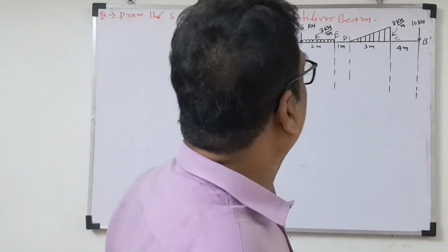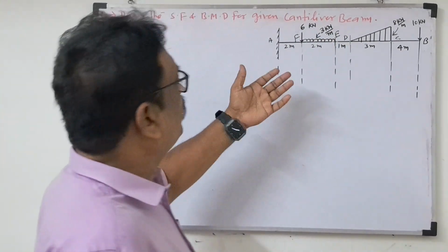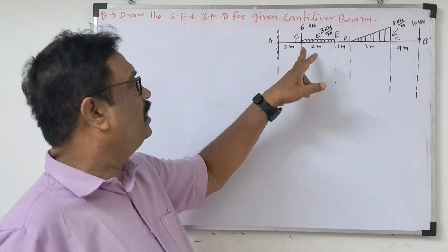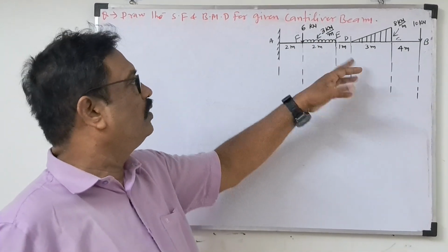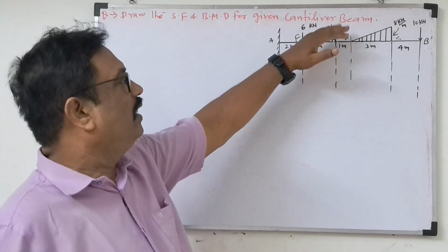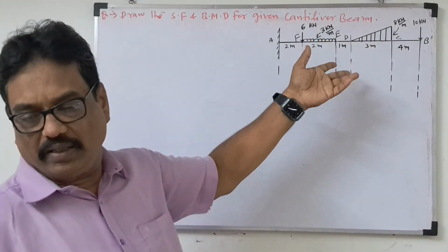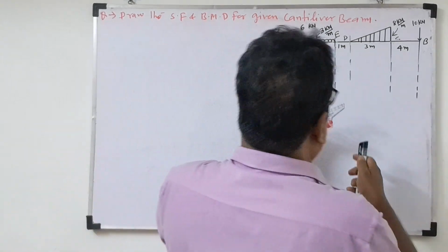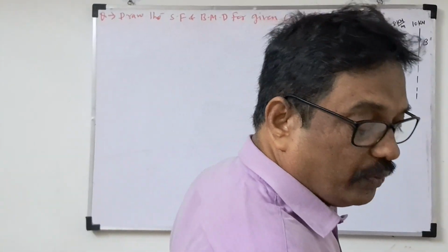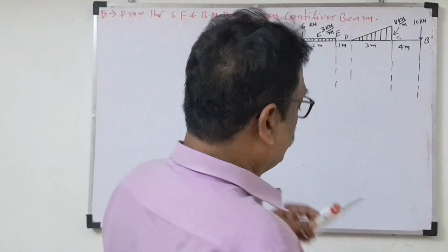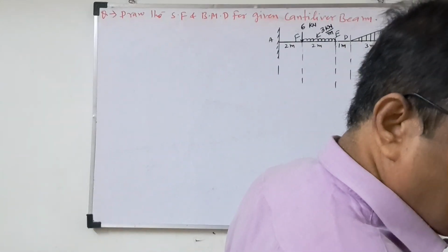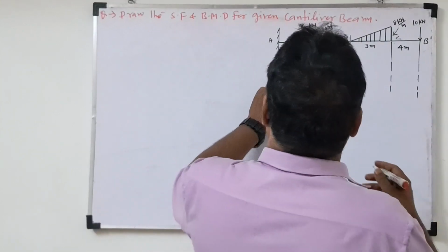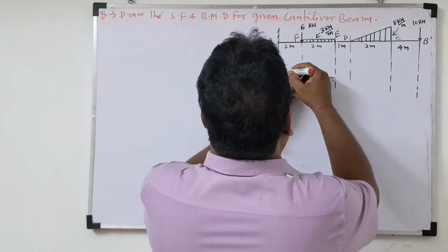Suppose sometimes in engineering mechanics they ask to find the support reactions. How will we find them? We add the total vertical force and horizontal force, and take the moment, and then you can get both support reactions. So the load diagram will be helpful to calculate the moment. I am drawing it just for your understanding.